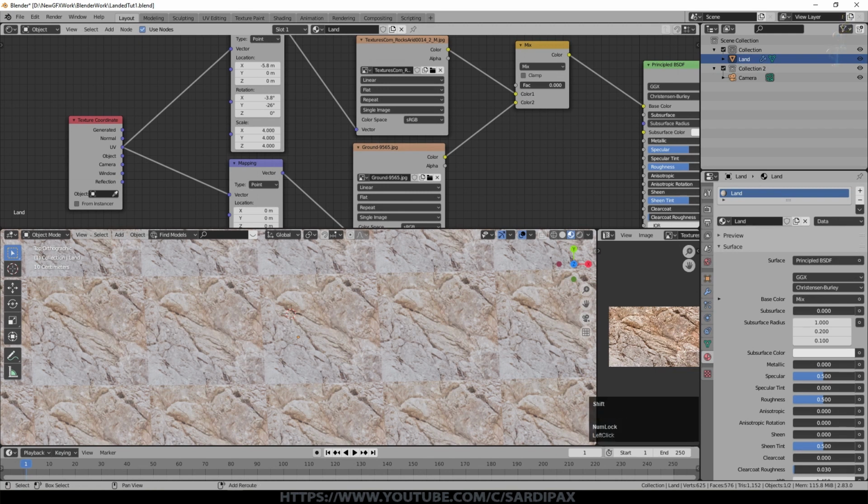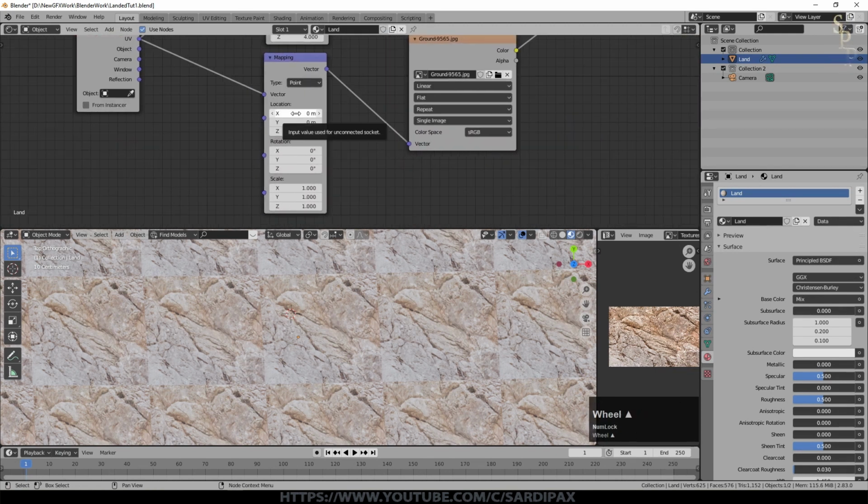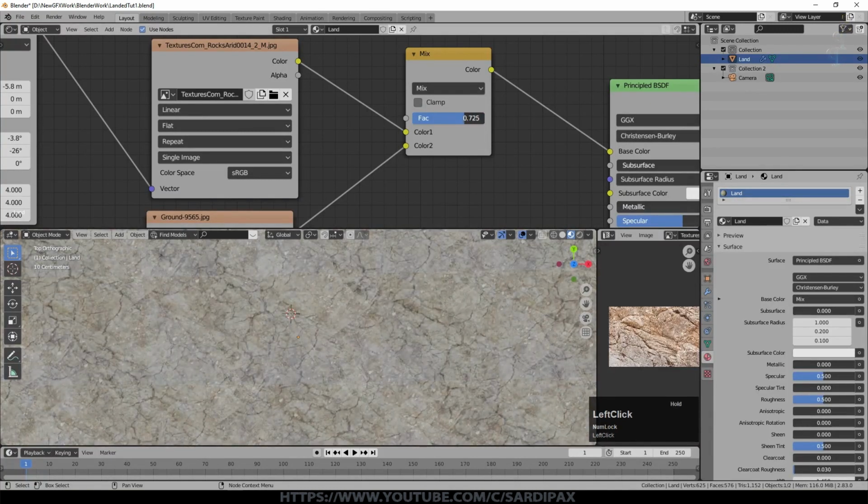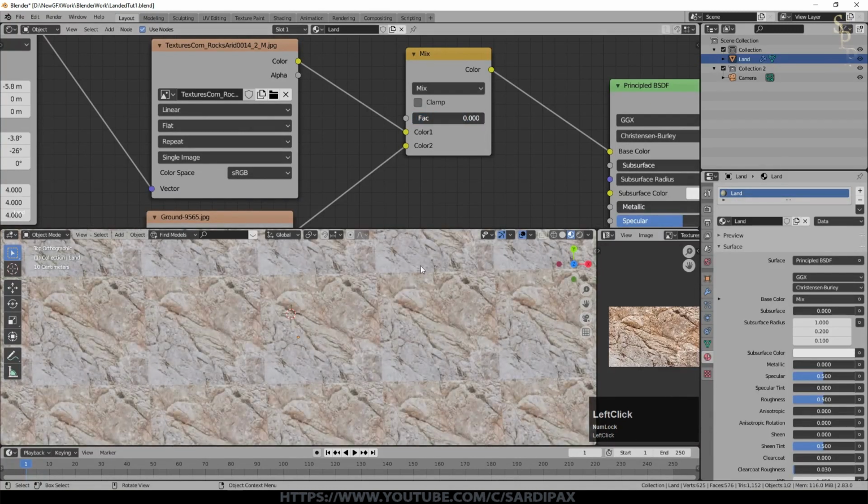What I also then did was put some changes into the other side. So I put 12.5 on here. These exact values are up to you. You will just need to really experiment and shift these around to see how this works for you. The main one that will affect it is actually scale and rotation. And I set the scale to 3 for the other one. So now when we switch between them, you can see the other texture is at a completely different angle and it's a different scale. So they'll start to work against each other in terms of those tiles.